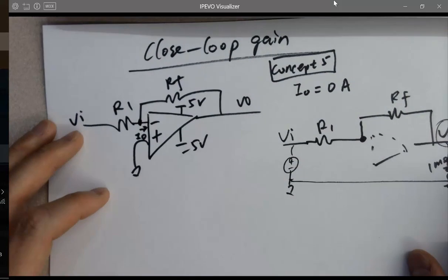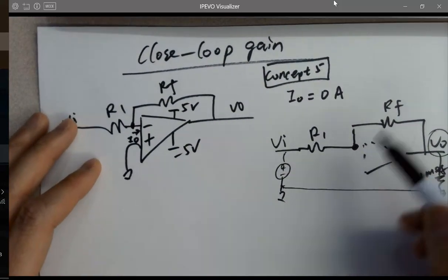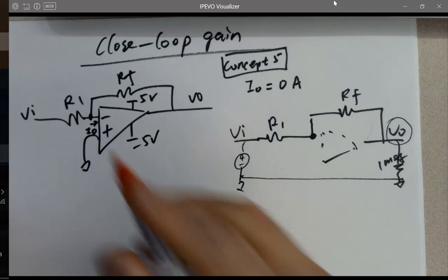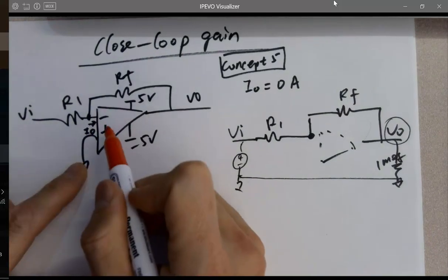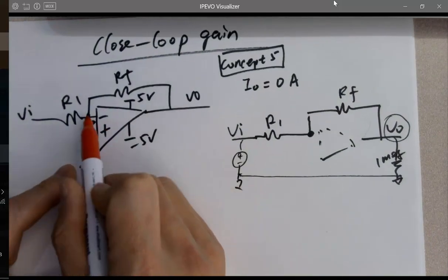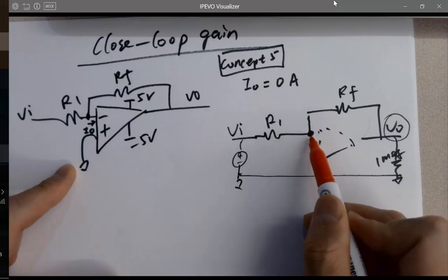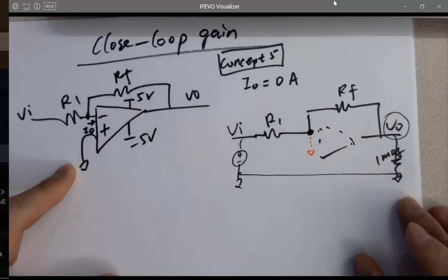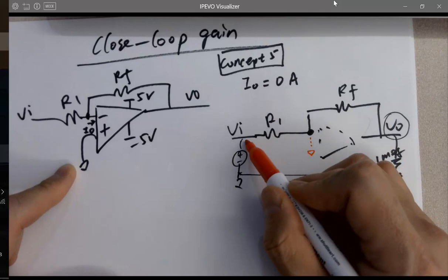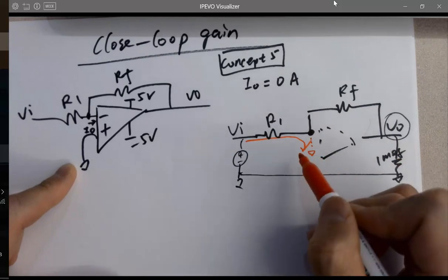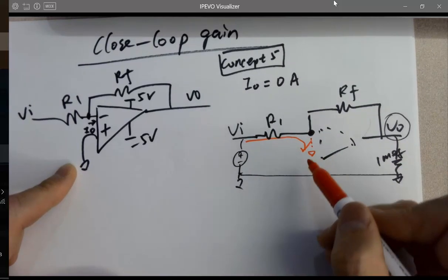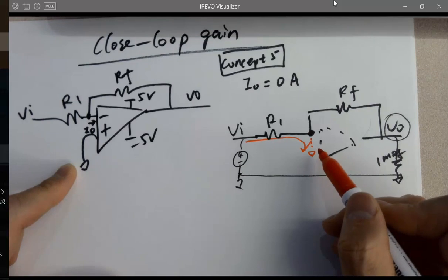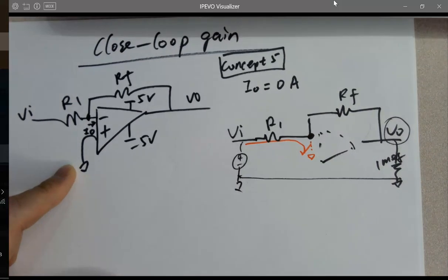Why is that? Let's still look at this resistor network, okay? After you put an op-amp in here, what's happening is you virtually grounded this point. So you drop this voltage abruptly to 0, a sharp drop to 0 volts.